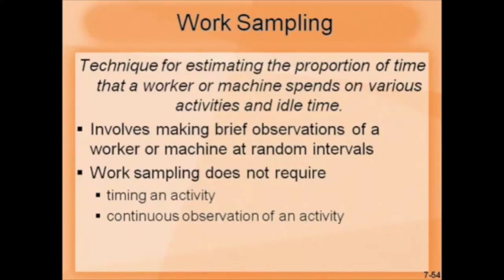It does not require timing an activity. Note that they are just coming and checking or observing if the machine is running. They are not collecting any data on timing, like how much time it takes to produce one unit. That type of data is not collected. It is just the observation. They may not even come with any file or pen or pencil, because that may have an impact on the worker. Even if somebody just walks through, the person working on the machine will not be conscious that somebody is constantly watching, or know that this is work sampling.